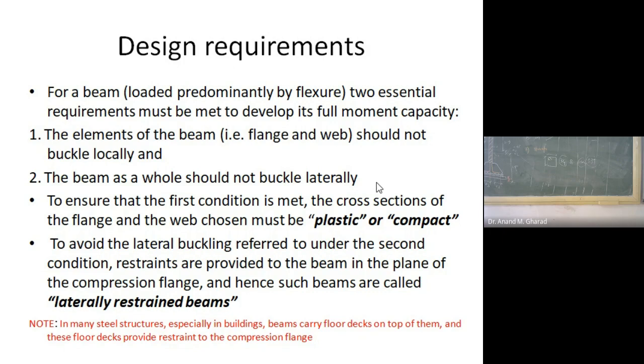You must have observed in the industrial buildings at various floor levels, concrete is done. These are again floors which are made up of RCC. But before that RCC, you will notice that there are some kind of corrugated sheets which are placed. Above these corrugated sheets, reinforcements are placed, and then concreting is done. That is known as metal decking. It is a permanent kind of structure wherein you will find these corrugated metal sheets embedded in the concrete itself. Okay?